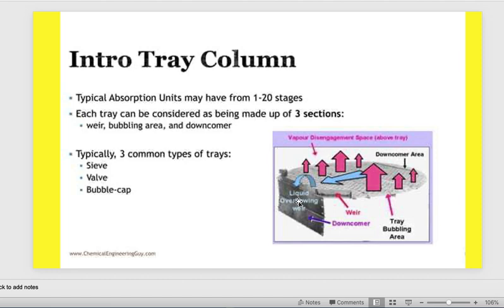This is to describe the liquid related to the tray. And if we need to describe the gas or the vapor, it goes up through the holes to the top of the tower, which is here in pink color. So you have to understand clearly the liquid behavior and the vapor behavior. The liquid normally stays here on top, then goes through the weir and down by the liquid downcomer. And here the vapor goes from bottom to top.